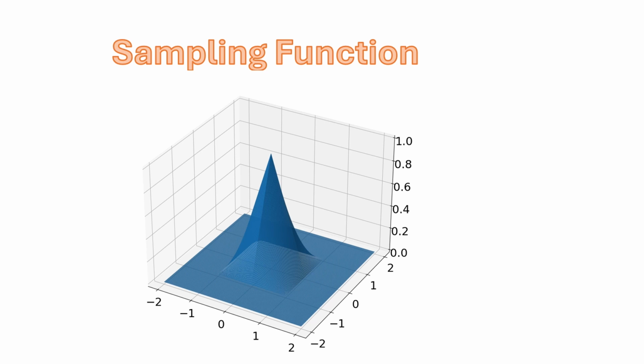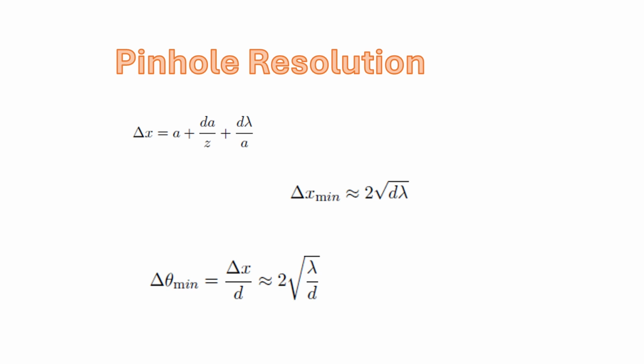Typically, we'd like to choose the pinhole or the coded aperture feature as small as we can, and then we would choose the pixel pitch to match that resolution, so as not to oversample, but so as not to degrade resolution. So we saw that the coded aperture feature size, you'd like to make it as small as possible, but as you make it smaller and smaller, eventually wave diffraction will dominate the size of the projected pattern from the code rather than just the shadow of the coded aperture.